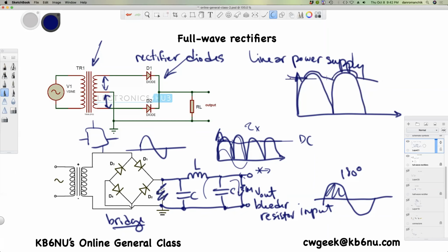So you kind of see we're getting closer to really a good DC voltage. Well, then if you put the inductor there, what the inductor does is it'll resist changes in current, and that'll help with the filtering. And then if you got another capacitor after that, it's even more. So eventually that ripple there, sometimes we call this voltage ripple, will get smaller and smaller and smaller. Good.